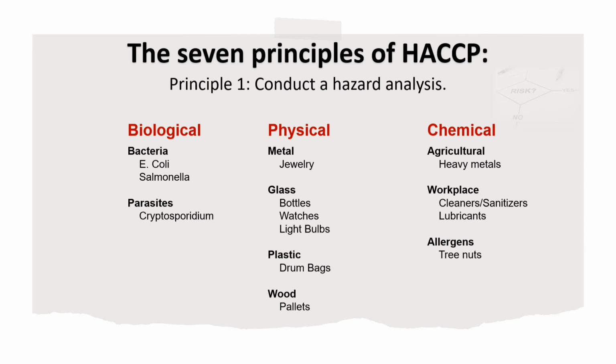And chemical hazards vary in the aspect of production they are related to. Some potential chemical hazards are the improper use of pesticides, chemicals used on processing equipment such as sanitizers or maintenance chemicals, or allergens. In this step you will need to make sure that you have the expertise to make an accurate evaluation of the hazards. The hazard identification is done in 2 steps, first the identification of hazards, then an evaluation of the hazard. The hazard evaluation is a determination of the degree of risk to the user from the identified hazard. Once the hazard is identified and evaluated, the team must identify critical control points. These are points where the hazard must be controlled, or it will present a risk to the end user.